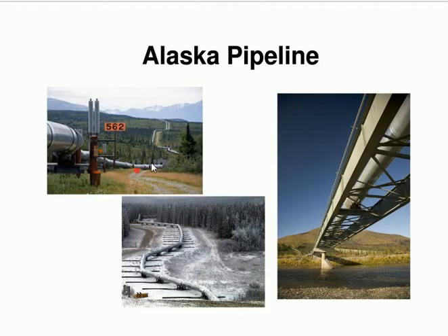Some pictures of the Alaska pipeline, and you can see some of the bends as well, which I think are put in deliberately to deal with the thermal expansion. So if they expand, they just move the bend a bit further out. You can see this here as well. So the stresses are not going to be across the whole pipeline, but only in some sections of the pipeline, and they give enough place to move in there.